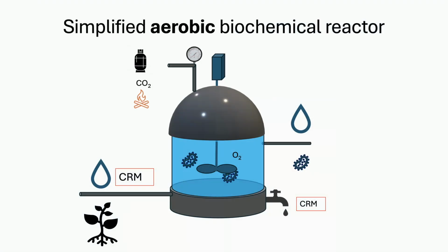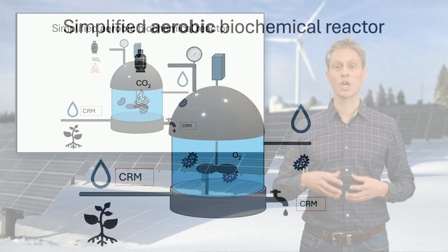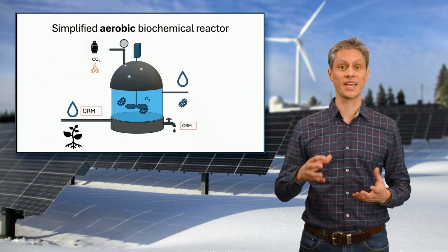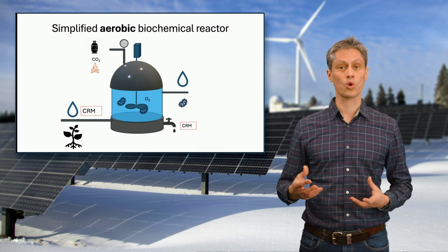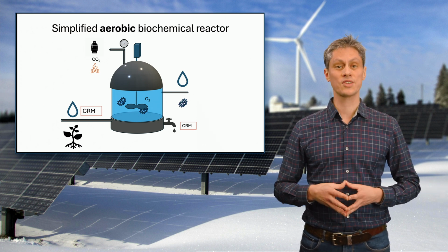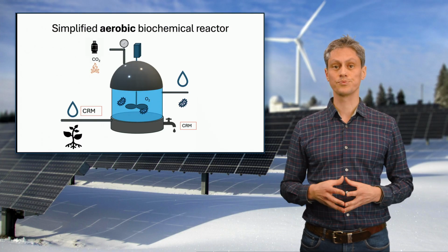The biological alternative to combustion is used in organic wastewater treatment, in processes also like composting. Microbes use biomass and oxygen for respiration. Some low-temperature heat, up to 70-80 degrees centigrade, is generated, but the process also yields new microbial mass and carbon dioxide.